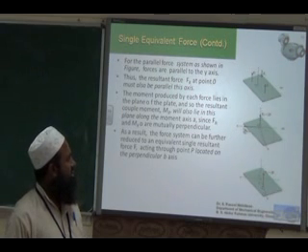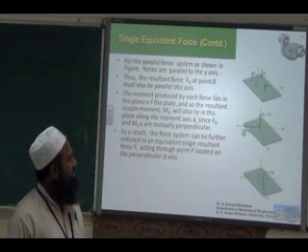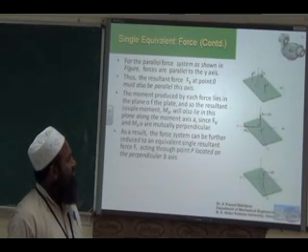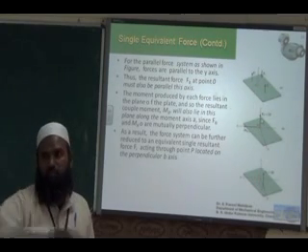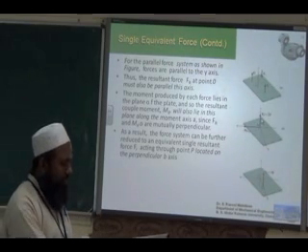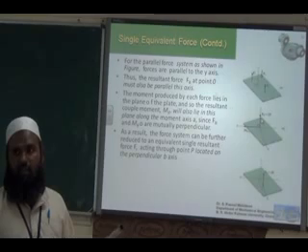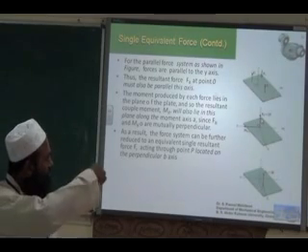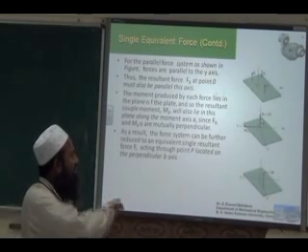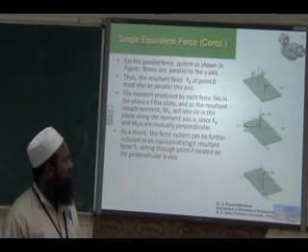We have three axes, X, Y and Z. So this is the Z axis, this is the Y axis, this is the X axis. So the forces are parallel to our Z axis or Y axis, we can say perpendicular axis. Then its moment will be in this axis, on the plane. Moment will be on the axis, parallel to the plane. Now perpendicular to that moment axis, we consider another axis, and you move the force to a particular distance. So it will have a moment equivalent to that moment developed because of all the forces.